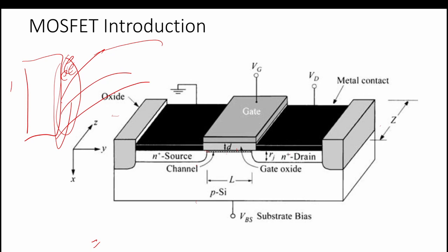Next, the source is a highly doped N++ region. We cannot dope it P++ because it won't connect. The N++ region is highly conducting, so that's why we dope it with a highly doped negative impurity, and it connects to the channel, which is doped the same way.